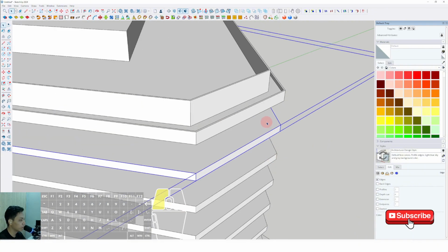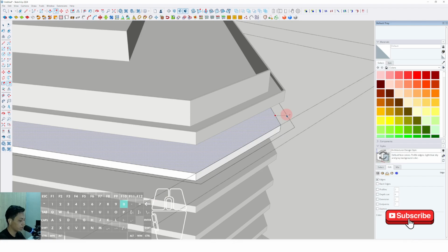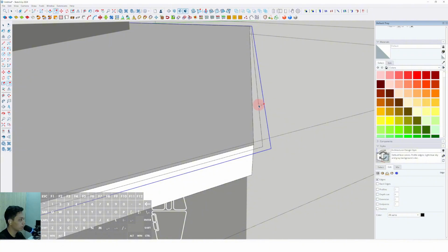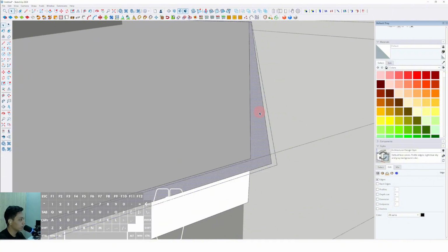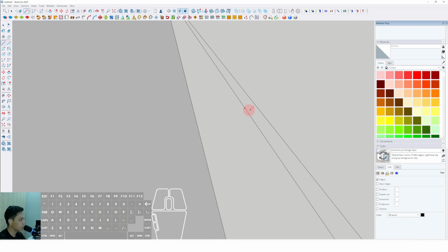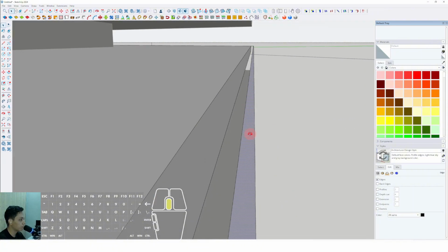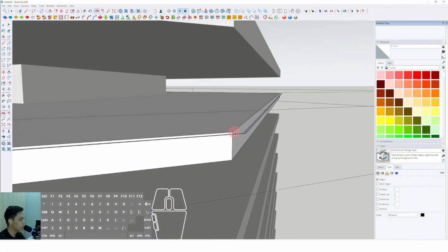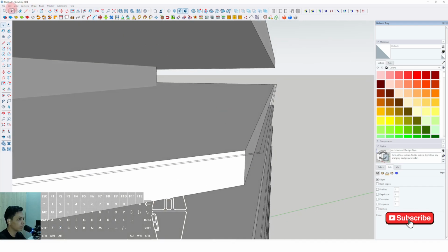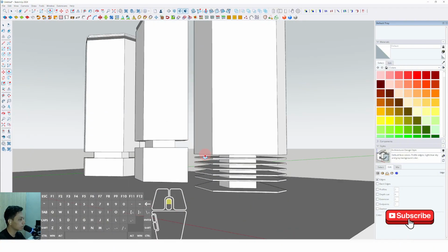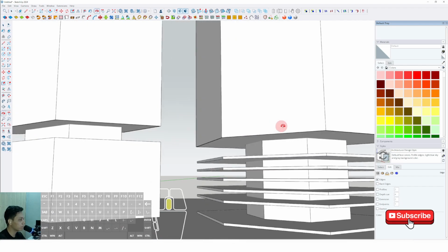this one and make unique and offset it outside around 500 millimeter, and delete this surface, and we have to offset it inside again around 100 millimeter, and delete this surface again, and we can select the line. Okay, then we can connect both of the lines until the surface of the plane of this glazing appears. Then we have to Control X, exit from the group, and then we can edit, paste in place and push it down until our desired position.